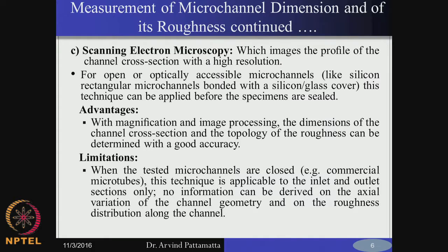Okay. The scanning electron microscopy is usually available if you go to either the chemistry lab, physics lab or materials engineering. So, usually they use this when they synthesize a new material at the nano scale, and they immediately have to characterize this material. Okay. So, they do use different techniques for characterization. One, they have to first identify what is the size distribution and how it is actually appearing. So, the physical appearance. That is done by using the scanning electron microscope.